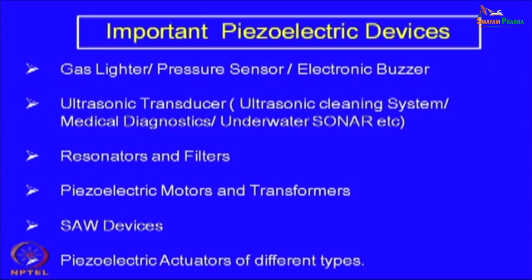We are not going into the details of the designs, but just using the basic principle of piezoelectric material or piezoelectric coefficient, one can design different kinds of load cells from a few grams to several tons. Okay. So, there are of course complicated designs, but at the heart of these sensors there is always a small piezoelectric material of the right property.